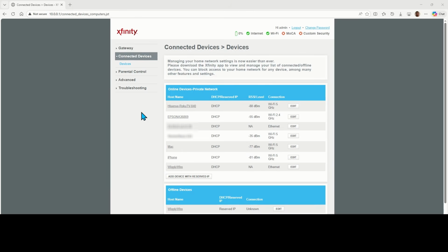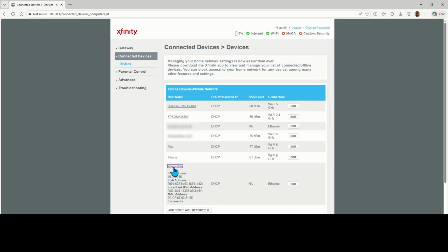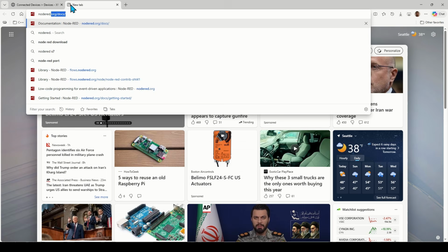Once the Pi powers up, we need to get the IP address that our router assigned. Go to your network admin page and check for connected devices. I'll view the IP address assigned. From there, we can SSH into the Pi at the IP address with the user credentials set in the Raspberry Pi imager. The first thing to do is install Node-RED.